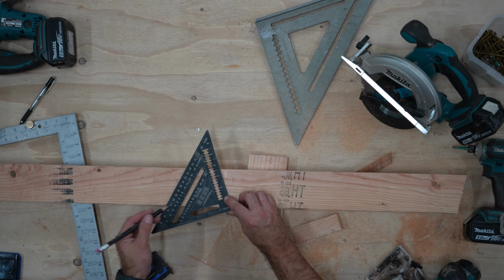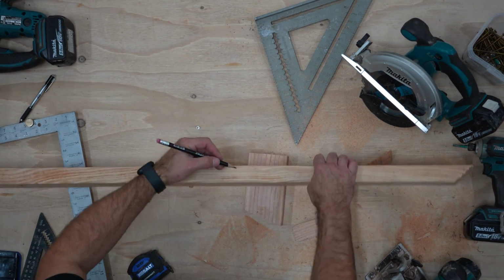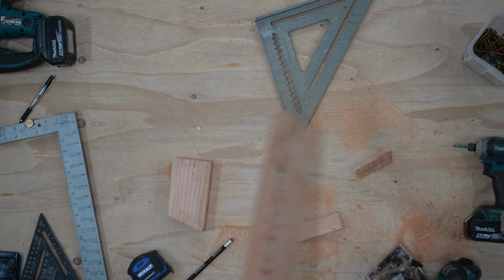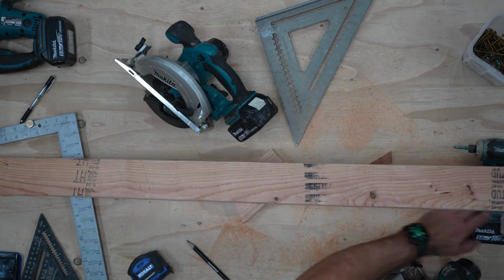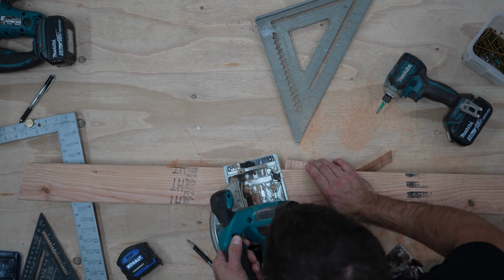So the easiest way to cut the bevel right for both of them is to find a board long enough to make both pieces and then cut the board in half. This will give two beveled pieces, each with opposite angles. Then just grab the first piece that matches your needs. That is what I did here.